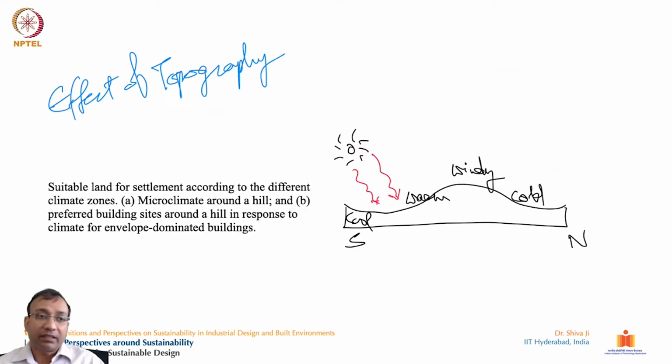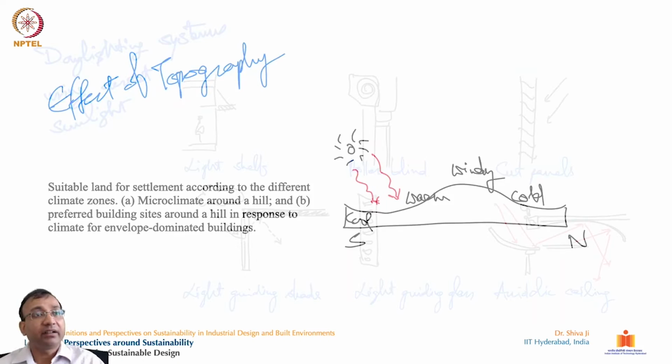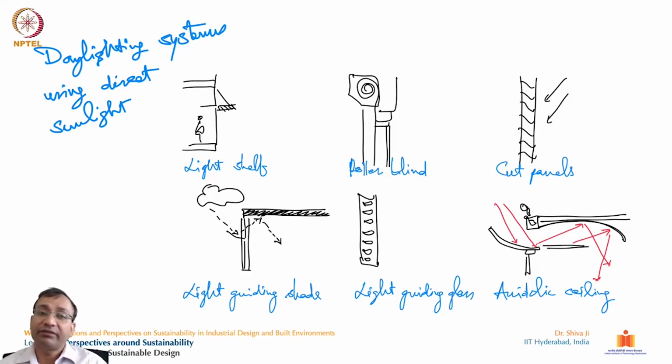Yeah, and the topographical effect as I stated earlier. For facilitating an efficient flow of light, heat, and ventilation, we have doors and windows. We have a number of solutions already existing with us for how we can facilitate this. Based on the width and height of these louvres, which come as vertical and horizontal members, the perforations and these pergolas, we can control the intake of light.